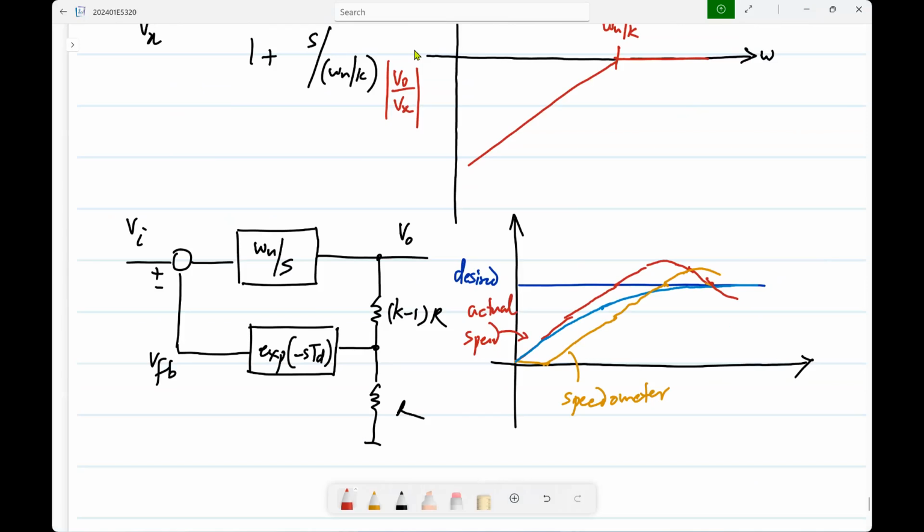That is, you know that let's say the delay is like 2 seconds and you accelerate gently enough that over those 2 seconds, the change of speed is not so much. Then you won't overshoot, or even if you overshoot, it won't be severe. Is this clear? So essentially, you slow down your system. Because you have delay, you may have had a severe overshoot. Instead of reaching 40, you go all the way to 60, come back to 20, and you keep doing that. That's very irritating. That's not a nice way to drive.